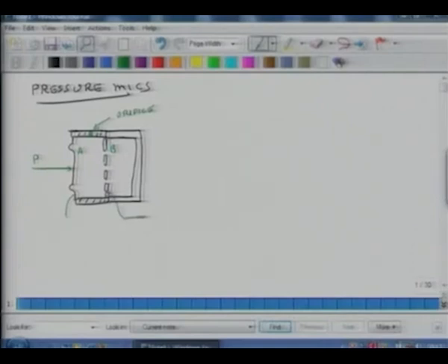are connected to a resistance which is a very high value of resistor. And then I have a battery source which provides what I call polarizing voltage. The diaphragm and the surface B are made of dielectric material, so they can store charge. Electrically, this entire thing looks like I have a DC supply, a very high value of resistance, and then these two flat plates make a capacitor.